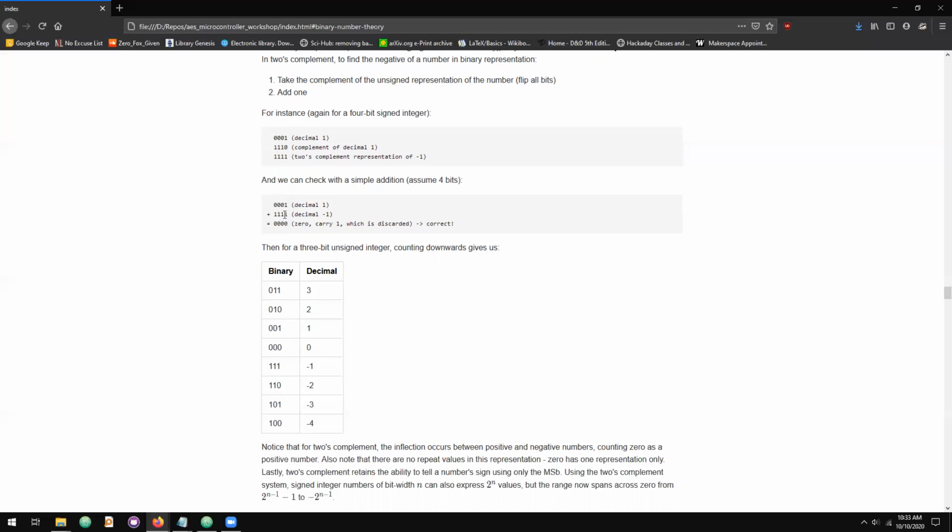And when you do the addition down here, as you would expect, that carry just carries into the new most significant bit. For this example, that's another 0 and another 1. So ultimately, it doesn't affect the result. So the number of bits that you're using to represent the number really matters because that determines what the format is going to be.